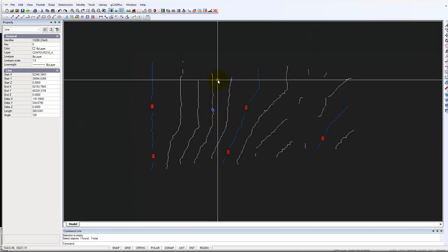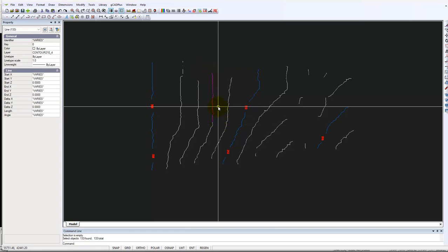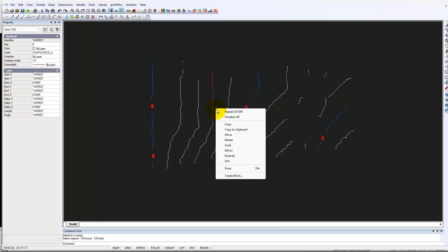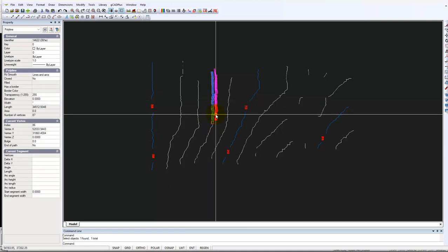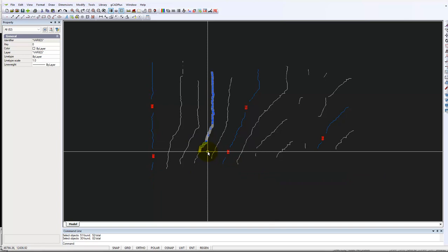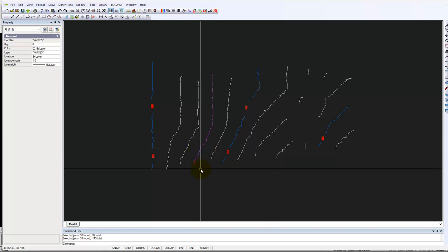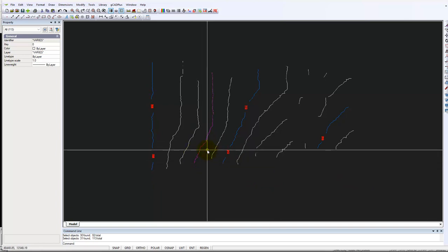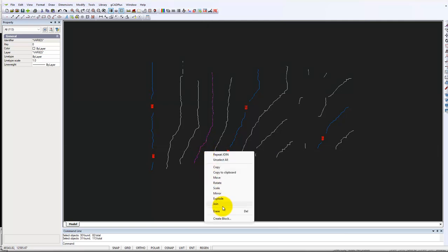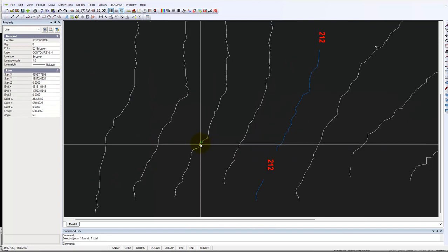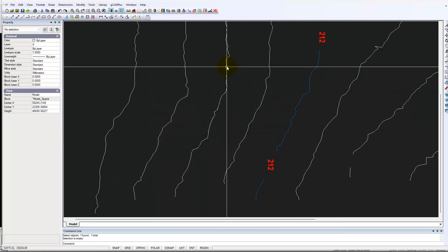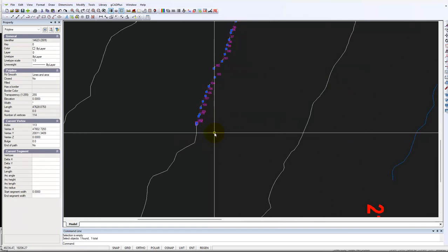So the way we try and deal with it is that we grab these and then in gCADPlus just join them and select that. We hope that's now one entity up here, one polyline, and then we just carry on, hopefully grabbing all of these, and if we're in luck, we should be able to simply join them. And you might have noticed little flickers of pieces that didn't in fact work. So let's come back. So we've got a polyline to that point there.